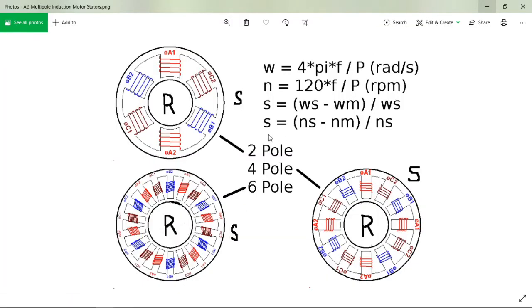Here again we see the pictures that we saw in one of the other sources. I went in and got rid of this. Those were DC motors where you had a magnet on here, but here for the induction motors, we have basically a stator which has a bunch of coils, and the ones for the induction motor are actually distributed windings. It's a smooth air gap. You don't have big breaks like this.